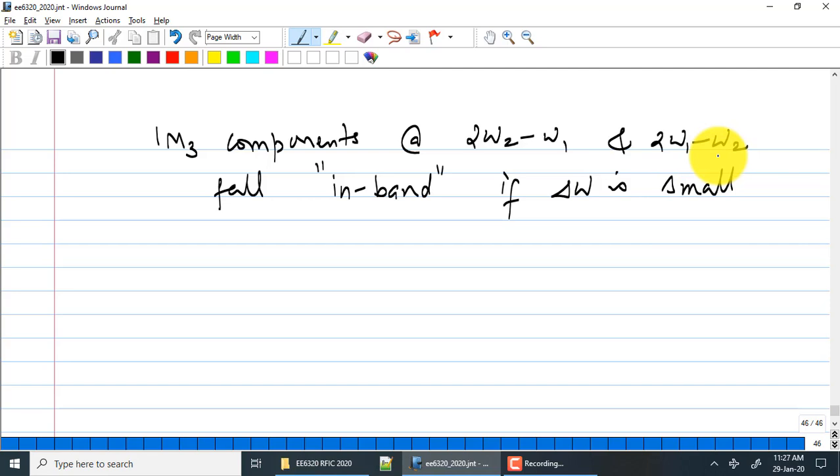So now you don't have to worry about the frequency response of your system. Because these two components will be functions of the nonlinearity of the system. Their amplitudes, if you did not have a third order nonlinearity, you will not get this component at all, because it depends on alpha 3. Make sense?